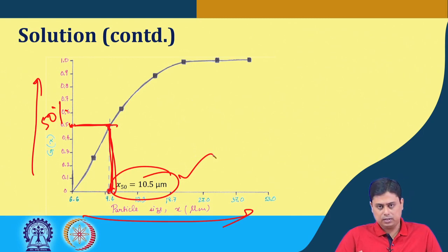I hope this is clear to you, that if we have the size distribution known of at least 2 inlet or outlets, then we can calculate the third one. We can also calculate the grade efficiency from the size range data. From that grade efficiency we can find out the equiprobable size.